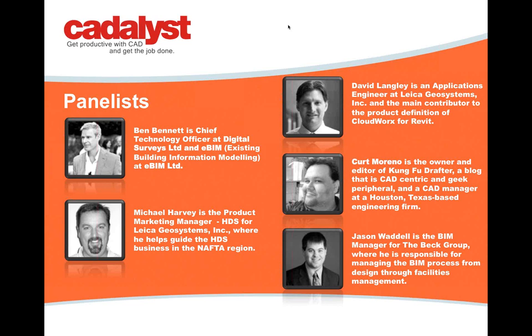Sure. Well, as far as hardware scanning equipment, of course, us being Leica would always prefer ours, but Cyclone will take in other scanners that are on the market. The main thing, as long as you get the data into the Cyclone software, then you're pretty much good to go. As far as computer hardware, I think David was using just your run-of-the-mill type of laptop. When you're buying a laptop or workstation for point clouds, one of the most important parts is the graphics card, because point clouds are a little heavy on graphics cards.